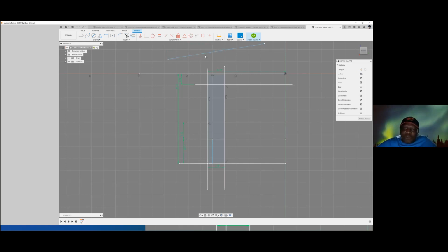And I want this line to be horizontal. All I do is go and put the horizontal vertical constraint. I put this and I mark this. So you can see that's another way to be sure that the line is horizontal. So if you're not sure your line is horizontal, and you want it to be horizontal, you constrain it to be